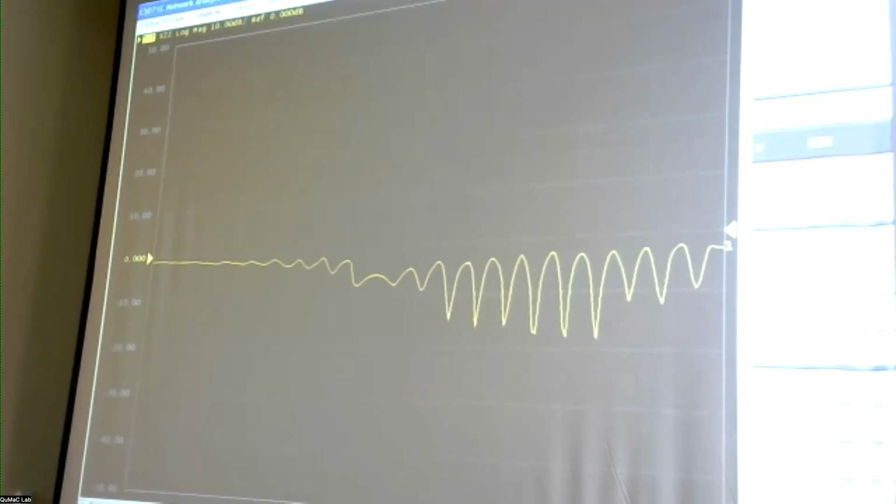That this particular one is able to give you the equal power split. So whatever power goes in comes out of these 2 ports, half and half. This particular one gives you 2 equal outputs, but it actually further attenuates the signal. So a factor of 2 in power is approximately 3 dB in power in log units. It's not exactly equal, but close enough. So it's often something you hear that 3 dB power loss means factor of 2. Again, numbers you have to remember. So 3 dB is factor of 2, 6 dB is factor of 4, 10 dB is factor of 10, 20 dB is factor of 100. Okay, so these are numbers you should get used to.